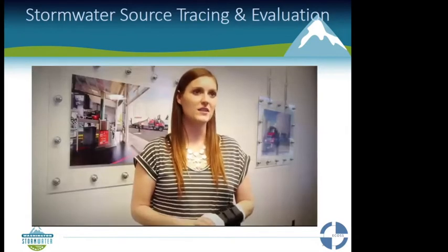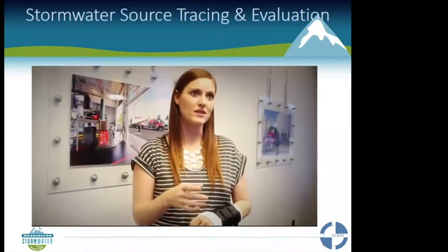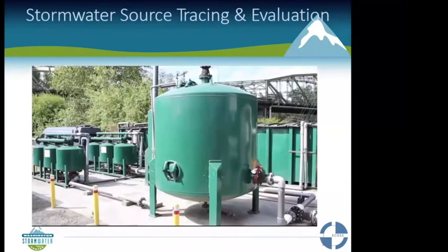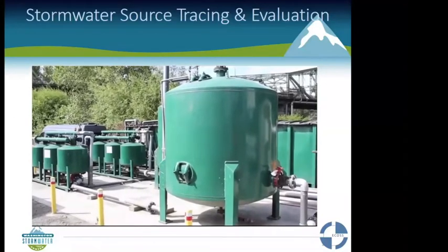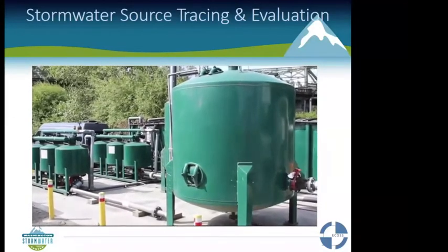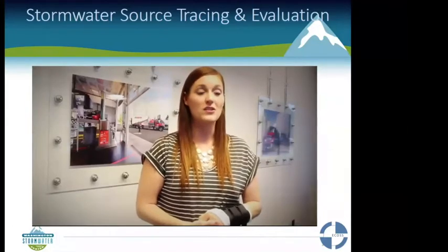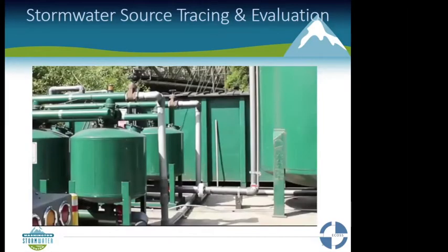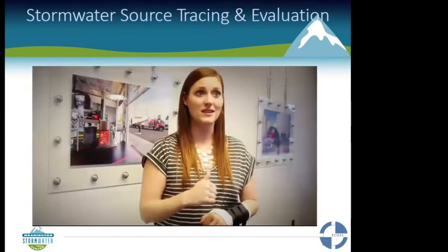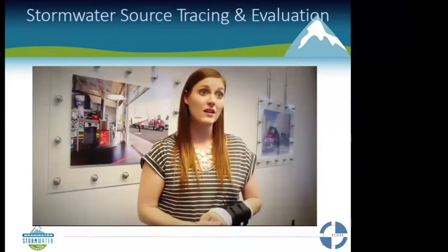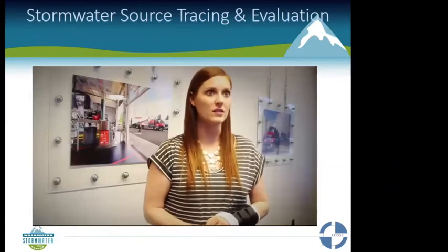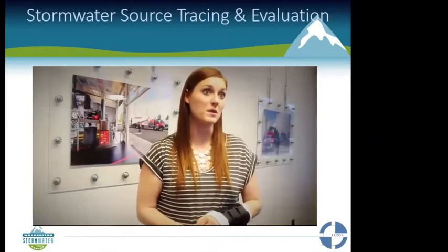After testing different catch basins and working my way towards the system, I looked at the treatment system itself. I decided to do some inline sampling and found that the zinc levels were different in the different areas of the system, even after areas that should have been treating for zinc. So from the inline sampling and the different things I found, we upped the maintenance schedule. Every time we do a clean out of this, we seem to see those zinc levels go back down. So we definitely kicked up that schedule and now find ourselves doing it quarterly, cleaning out the entire system, which is a bit of an expense, but I feel it's completely worth it to ensure that we have the zinc levels where we want them to be.